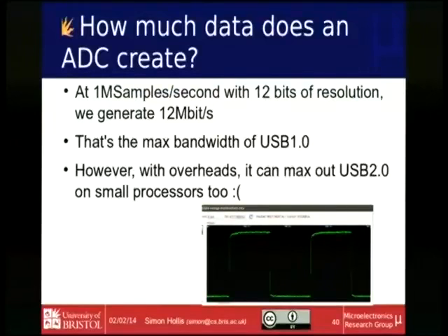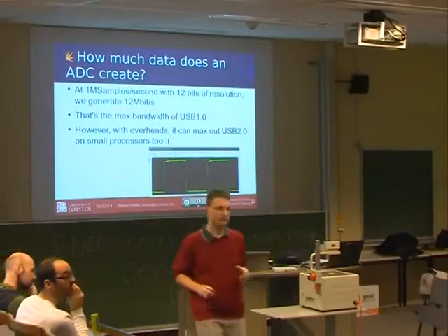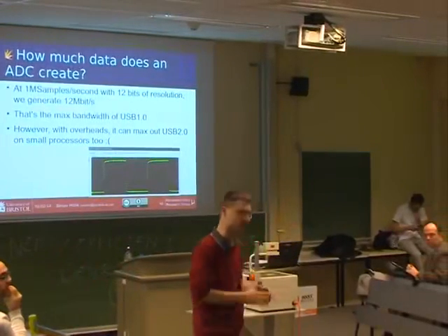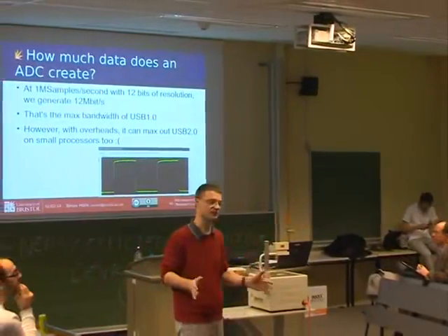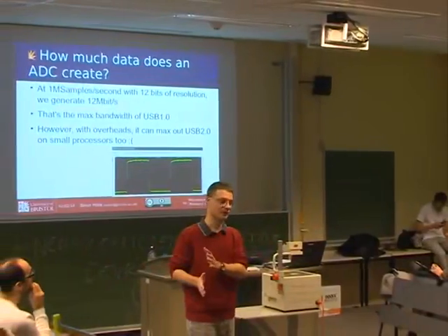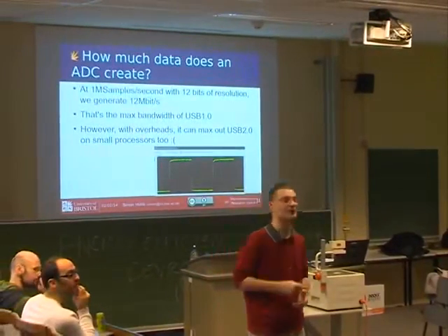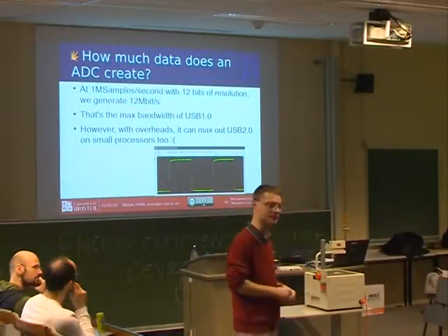Excuse me, how do we have to interpret this precision? Half an LSB, the least significant bit. So you've got a 12-bit representation. The bottom bit is 0 or 1 plus or minus 0.5. Yeah, I think it's capital B. You're right, sorry. Yes, the bit.